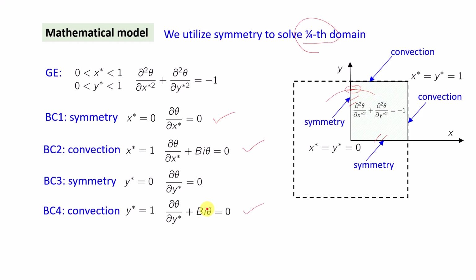So now our formulation is complete, but let me give you a caveat. Don't use this all the time. You have to look carefully into whether there will be symmetry. The symmetry condition is restricted to linear problems only, and this is indeed a linear problem. So you have to have geometric symmetry, boundary condition symmetry, and then the overall problem must be a linear problem. Then only can you have symmetry.